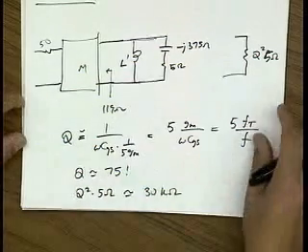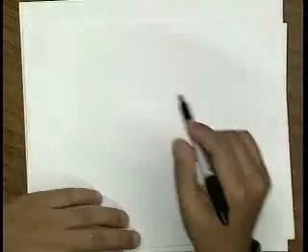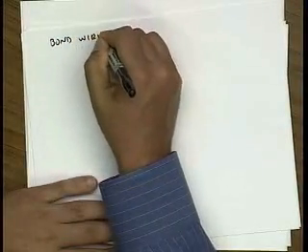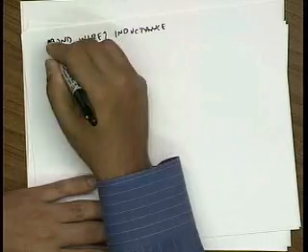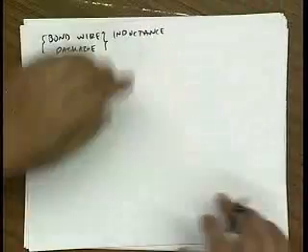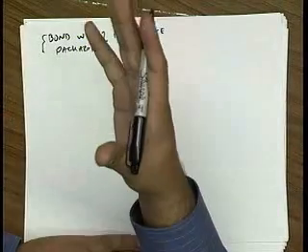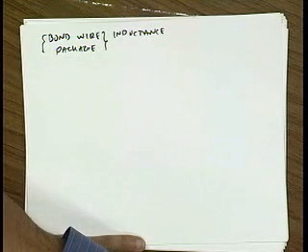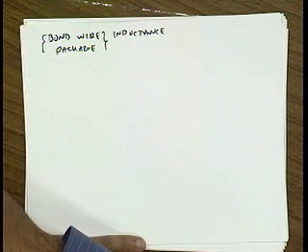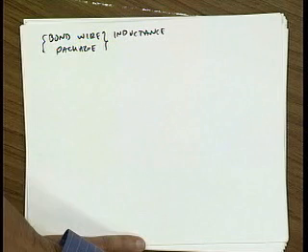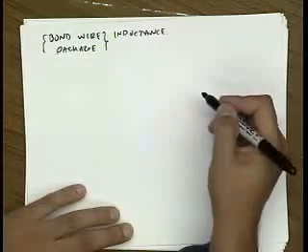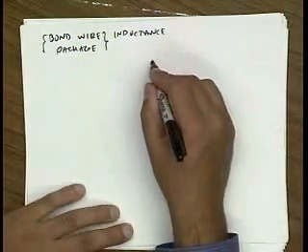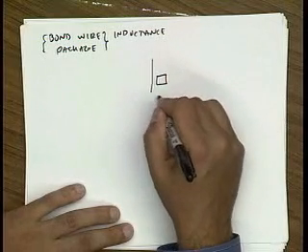All right. Well, last lecture, you guys remember that we talked about bond wire inductance. I should say bond wire and package inductance. If you ever build an LNA, even if it's on chip, it has to interface with the external world. Usually your antennas are not on chip. Say at a gigahertz, the wavelength's 10 centimeters, so even quarter wavelength is 2.5 centimeters, right? So at a gigahertz, you can't put an antenna on chip. It's just physically too large. So the antenna's got to be on the board or some external place. That means that you have to go from a board to a chip. And that interface, drawing it very crudely again, involves going through lots of parasitics.